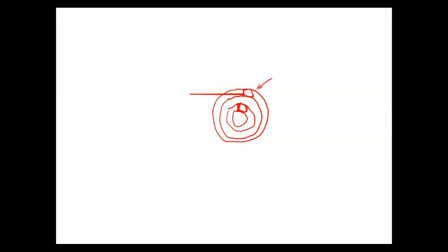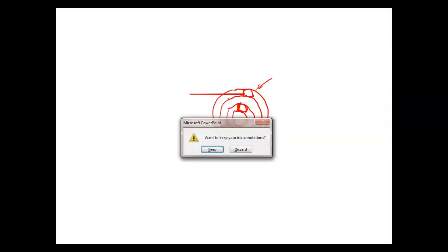Oh yeah, probably about 150 or more. The problem is they usually seal them up so good now. They usually put the rectifier assembly, everything in there, and they seal them up so good that you usually have to have special tools to get them apart. So they're not as easy to fix as they used to. But normally it's just the brushes that are worn out on the alternator.